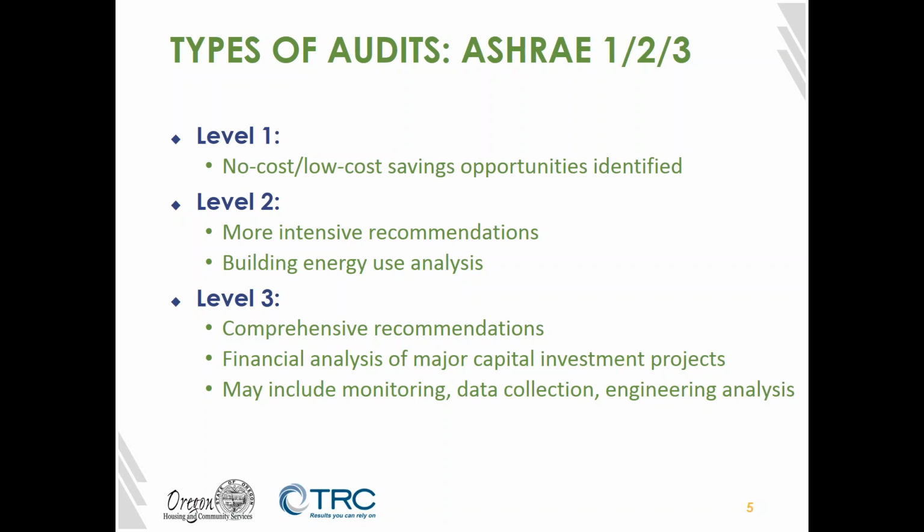In level 2, we start looking at replacing systems and getting a little more in depth with analyzing the building's energy use. And then level 3 is the full package, looking at comprehensive recommendations, changing system types, and doing a financial analysis of how much it costs to do the energy upgrades versus how much will be saved. It can even get into monitoring and collecting data on how the systems are currently used.